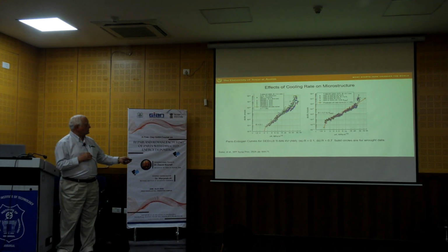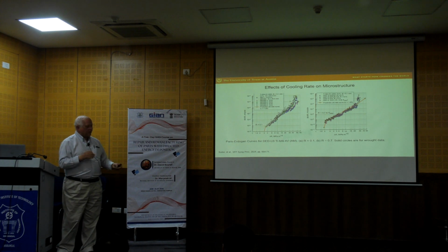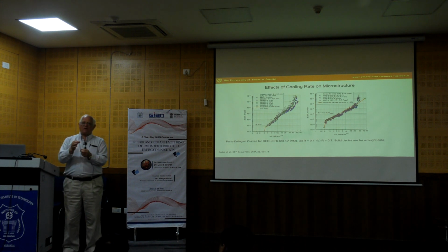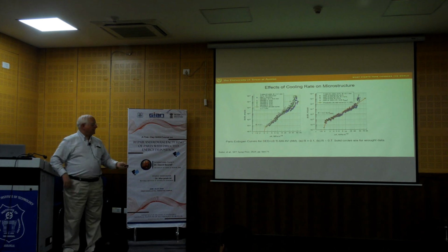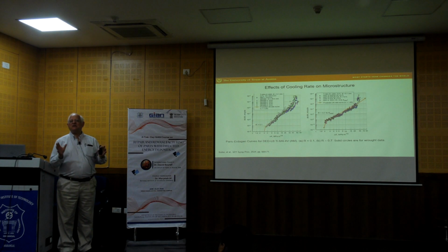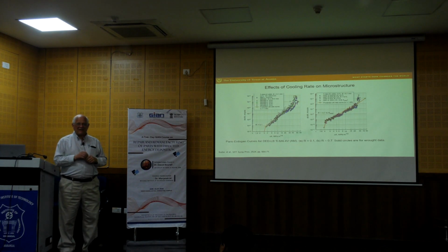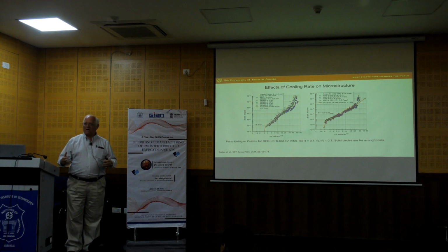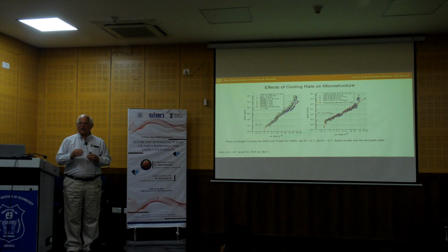For R equal 0.7, over here, it means that the minimum and maximum stress are pretty close to each other, right? And the effect of that is basically it's a gentler fatigue test, is the way I think of it. So the material can respond better as R gets bigger.